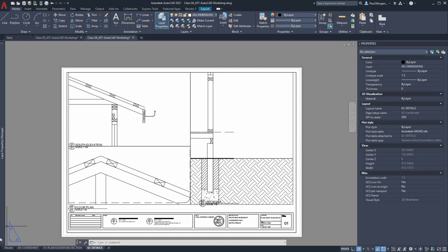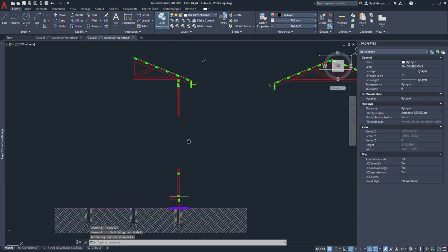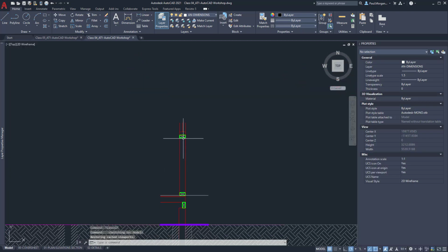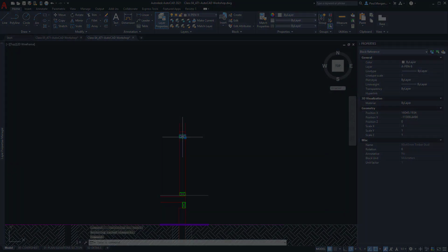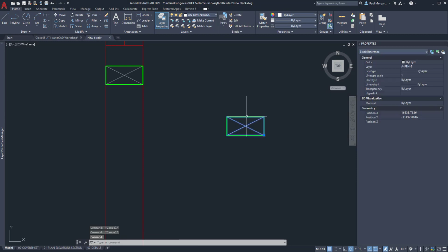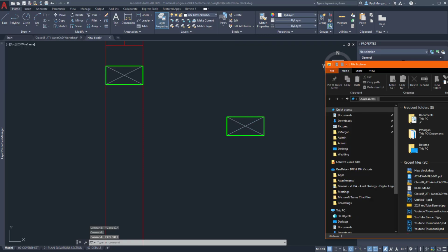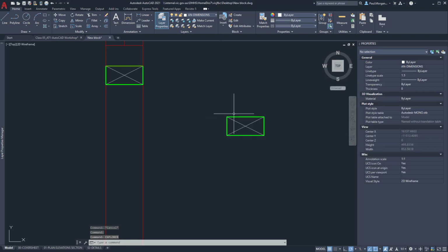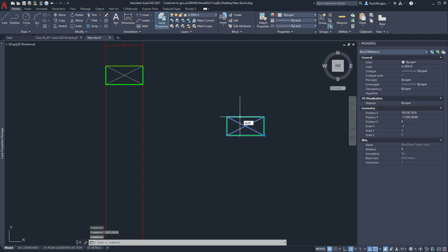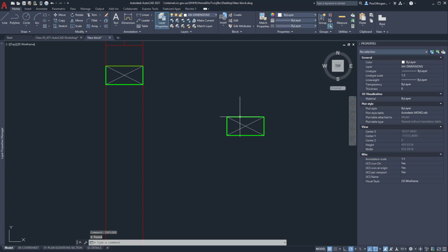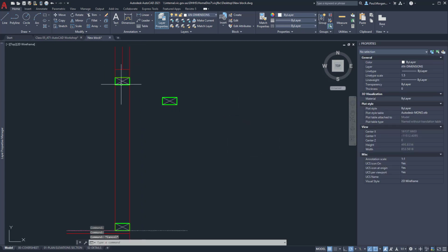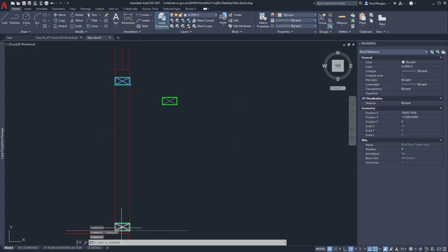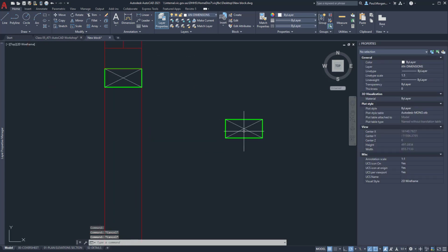So what we've got to do now is a little bit tedious, but it's about going in and upping the line weights for those blocks. So what I'll do is select the block, explode the block, and then we are going to recreate this block. So I'll go explode. Okay, so that block's now broken back up. You still have the other blocks to the left, nothing changes there, all the other blocks are still intact. This version has been exploded.